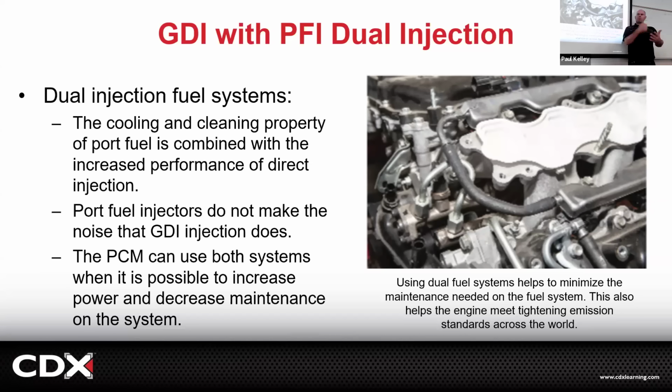Bingo. So he's like, hey, it needs a direct injector. But knowing that it has a cylinder imbalance code, cylinder imbalance more means you've got one cylinder that's running a little more rich or a little more lean than the other ones. These cylinders are not balanced. He was like, hey, you know what? It's a V6. You probably really need to do 6 injectors.